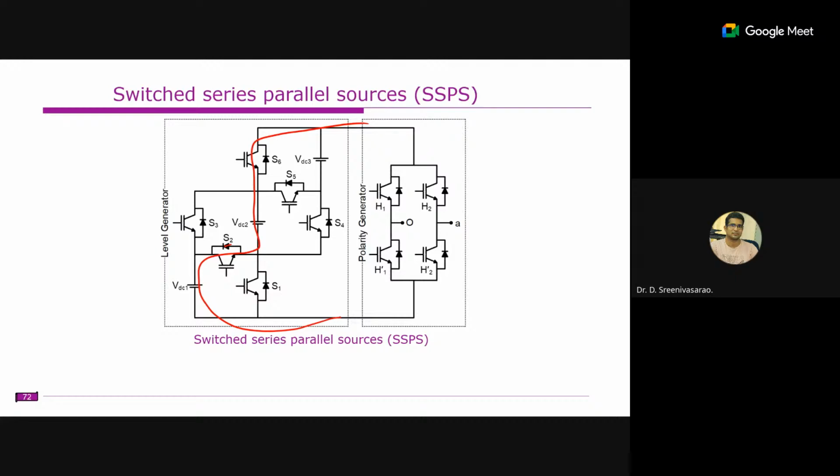That means if you compare these two topologies together, you can say it has a smaller number of switching devices. There you require 6 devices, and here also you require 6 devices. But the point is that we have reduced the number of switchings. For example, you require only one VDC, it will be like this. Now also you turn on 2 switches.